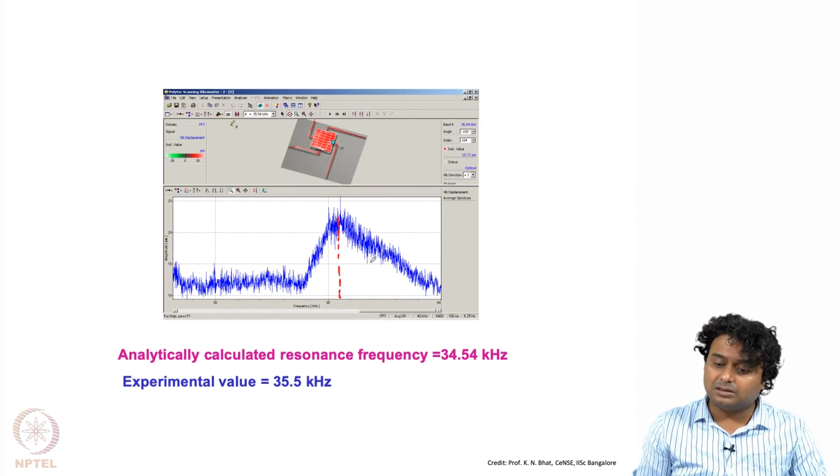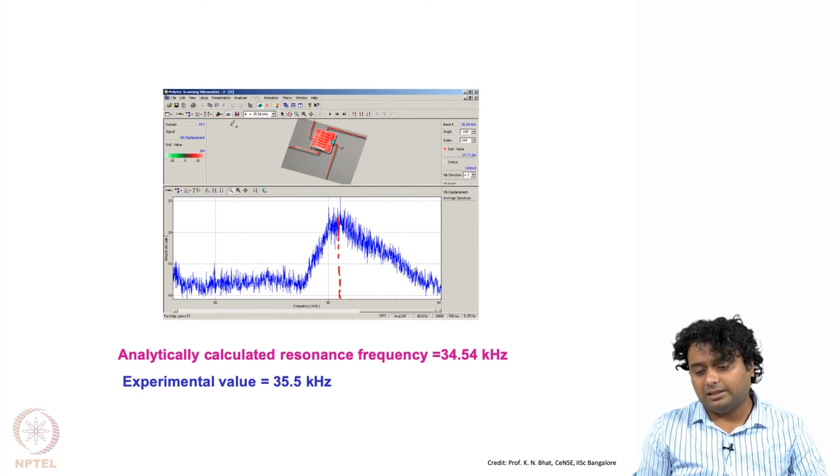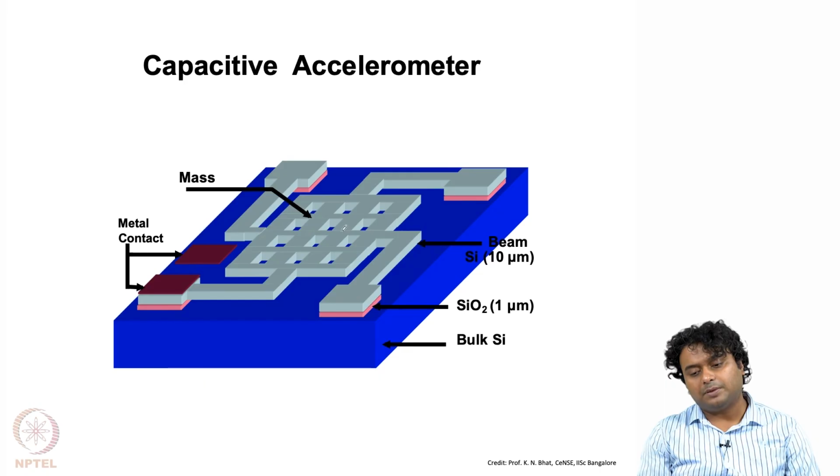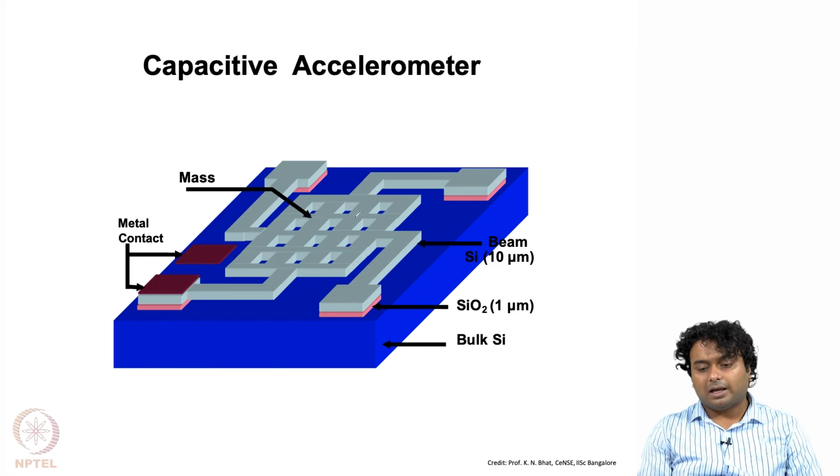And again, if we increase the forced vibration frequency more than the resonance frequency, then it decreases. While the structure is under some applied force, this frequency changes. Initially the membrane or proof mass is vibrated with some basic forced frequency. As soon as some acceleration change occurs, we will see a change in the frequency response, and accordingly we can measure how much the acceleration is.